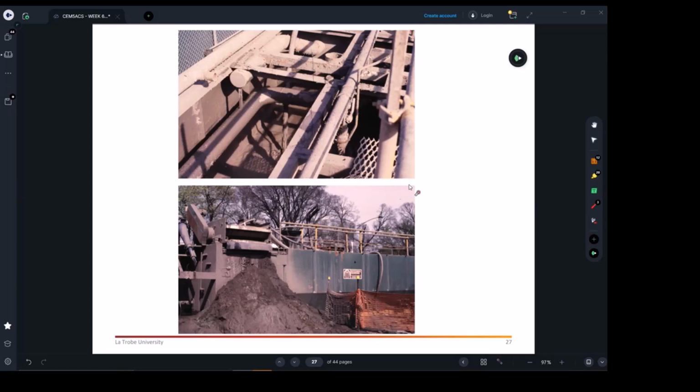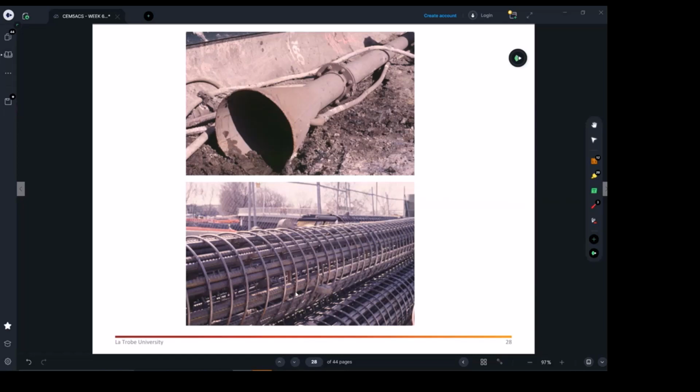This one shows you, as we said, what it looks like after drying the bentonite, the used bentonite or the new bentonite. As we said, it's a fine clay product which will be mixed with water. The bentonite, in the end, is a pure clay material that will be mixed with water and create that gel product to do whatever propping technique it needs to do.